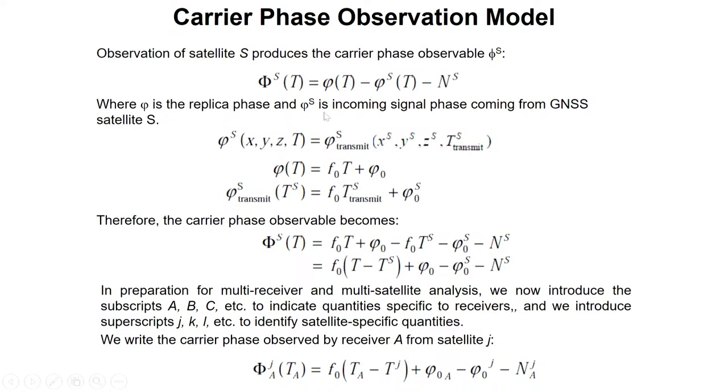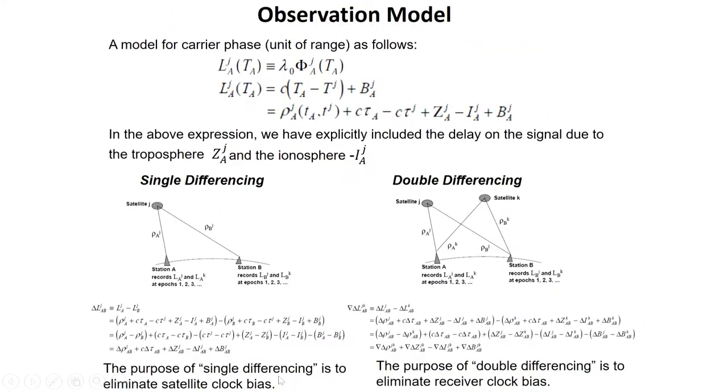When we implement the previous equation for this carrier phase model generation, we get this equation, where there is a time delay and a phase delay and some more errors associated with the signal. So we want to correct all this. We want to first estimate all these parameters so that we can do the correction, and then we can estimate the precise phase. When we get the precise phase, we use it for estimation of the unit length, and this is the formula to estimate the unit length.